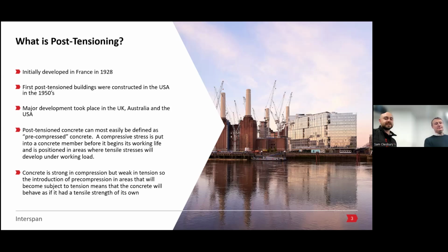So compressive stress is put into the concrete member before it begins its working life, and we position the post-tensioning system where tensions arise. As we know as engineers, concrete is strong in compression but weak in tension. So the post-tensioning system helps us overcome those limitations.